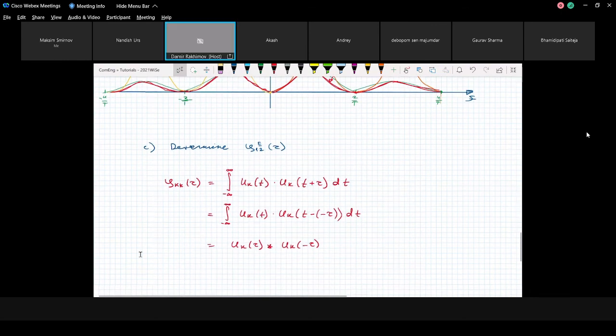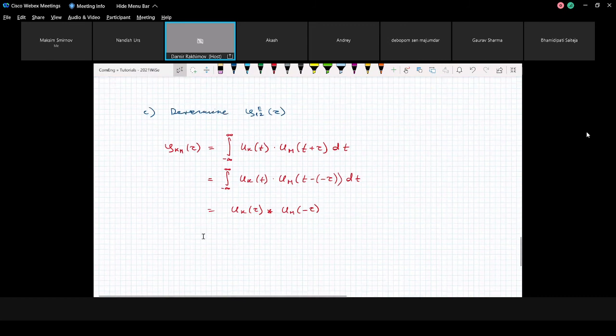When we calculate cross-correlation between, let's say, K and M signals, we have the first signal as it is, and we shift the second signal, Q of M. This expression gives you the algorithm of what you should do. You write your first signal as it is, and you put a copy of the second signal and start moving it to the right and to the left. Again, analyze what's the overlapping area between two signals.